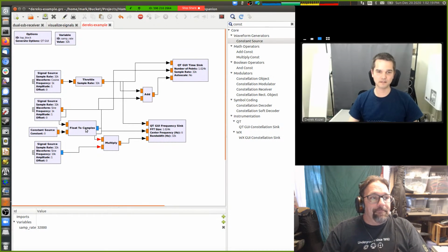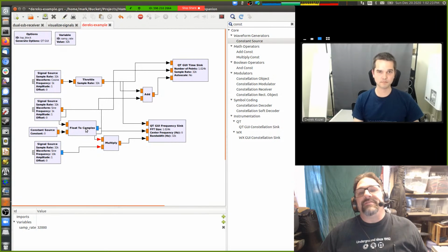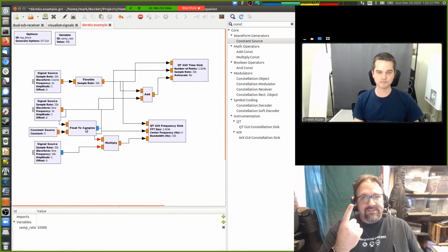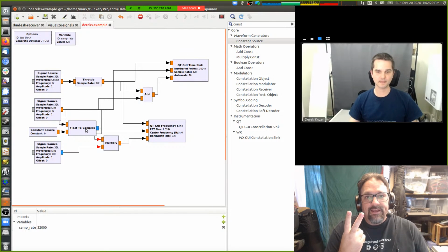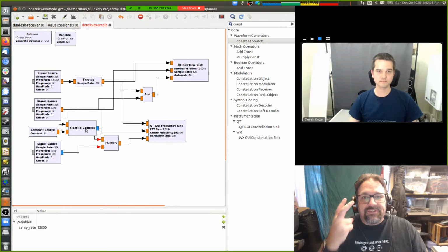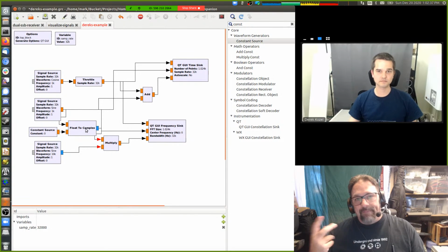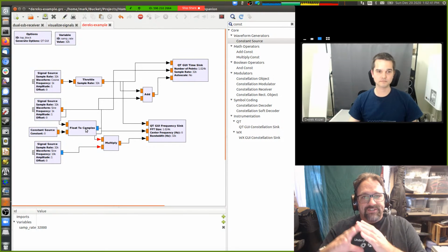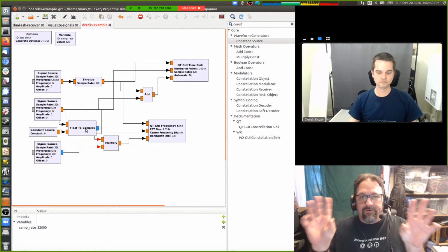So when you're measuring the complex impedance of your antenna, the two numbers are the resistance and the reactance, right? But there's nothing special about that reactance to make it a complex number. All it is, is a two-dimensional number, and they just happen to assign one of them as this square root of -1, which kind of puts it in a realm where the two numbers will never mix, right?